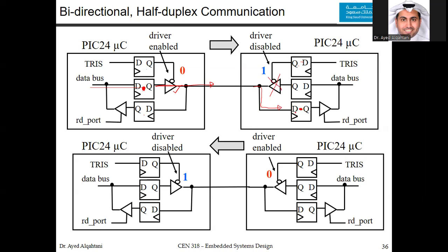And you can see that there are so many other buffers with different functionality. For this buffer, it's obvious that it's connected to a read port. So if you want to read the value, this buffer will be active, and it will connect this line to this line. And this way, you will read the value all the way to the bus inside.